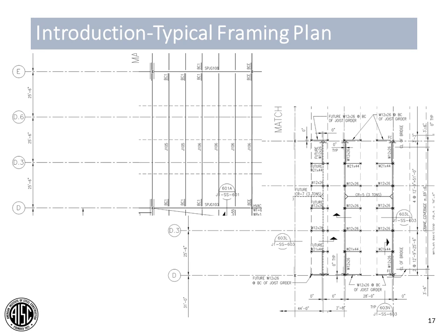What we have here is a plan view of a joist and joist girder structure. This plan in the upper left shows your joists spanning top to bottom on the page, and your joist girders are spanning left to right across the page. On the bottom right would be your crane runway system. The crane is identified here as a 3-ton system. And then we have these longitudinal members, which would be your runway members. And these smaller assemblies would be some infill steel, which you can see in this next slide.